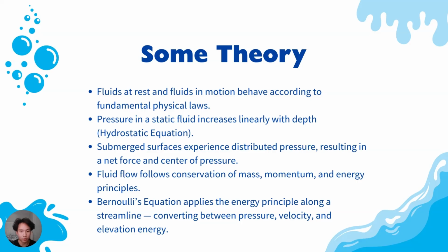The most important one for us here is energy conservation, which is captured in Bernoulli's equation. It shows that as fluid flows, its pressure energy, kinetic energy, and potential energy trade off with each other, but the total energy along the streamline stays constant. This theoretical foundation is what allows us to model and design systems that handle fluid pressure, flow, and forces.